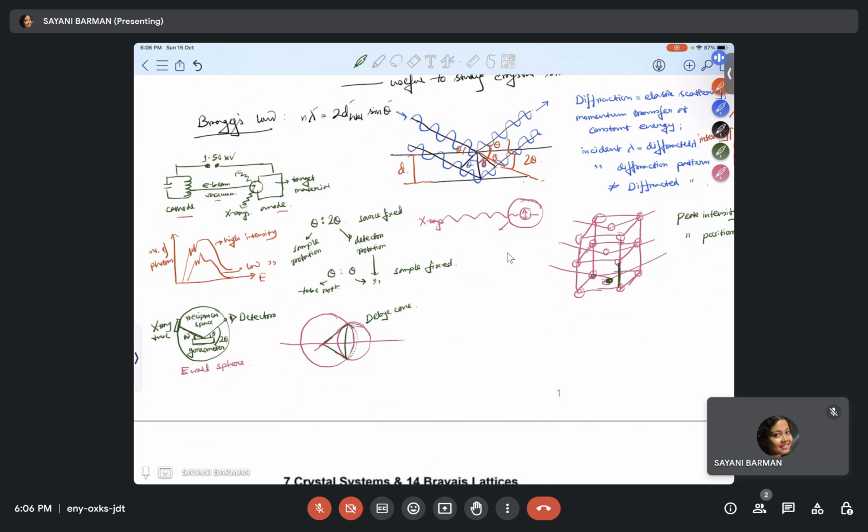Basically, in a powder pattern, all orientations of the crystal plane, and hence all positions of the powders, are allowed. So, in a polycrystalline solid, crystals are randomly oriented and they produce continuous Debye cones, right? Now, the detector scans through an arc that intersects each Debye cone at a single point, thus giving the appearance of a discrete diffraction peak.